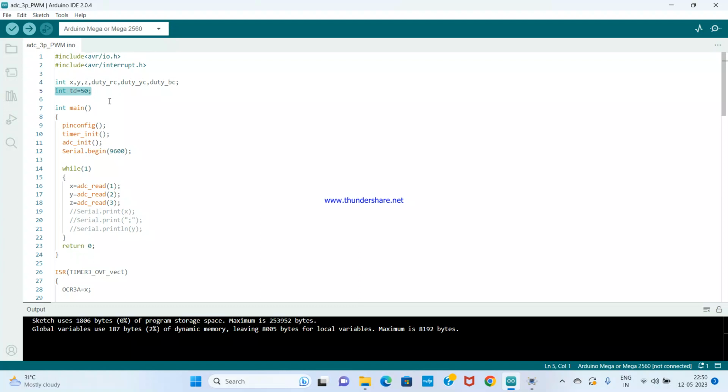I already explained how to decide that dead time. You have to read the IGBT or the MOSFET datasheet, and from there only you have to predict this. And how to predict, I have already explained. You can see some of the lectures on that in my channel.